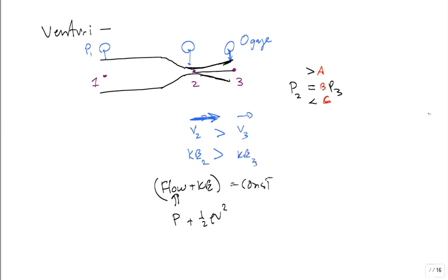83% correct. Got it? It's C. The pressure at 3 is greater than the pressure at 2. Pressure at 2 is the lowest pressure. Okay, let's say pressure at 3 is atmospheric pressure. Reasonable? Now, what about pressure at 2? It's below atmospheric pressure. You have a slight vacuum. You can use this, and a lot of tools and devices use this to great effect.